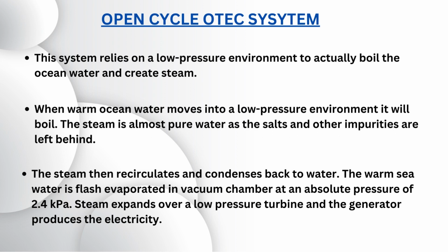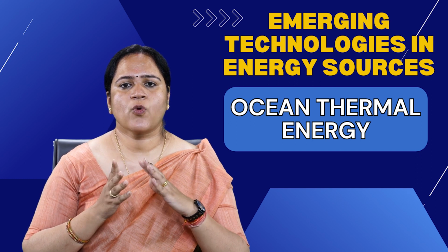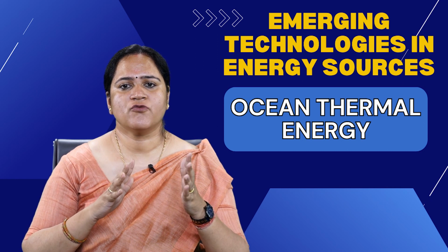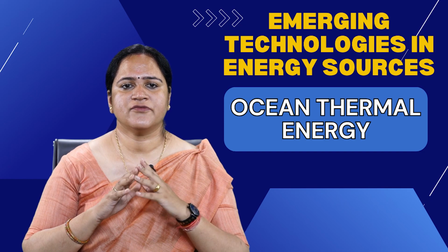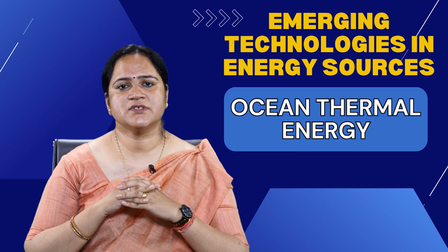The warm sea water is flash evaporated in a vacuum chamber at an absolute pressure of 2.4 kilopascal. The steam expands over a low pressure turbine and the generator produces the electricity. The pump work required in an open cycle plant has to handle a very large quantity of warm and cold water because of the low water temperature difference. We have discussed closed cycle ocean thermal energy conversion system also.